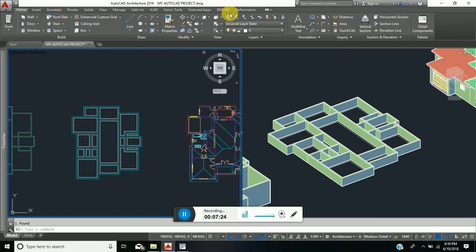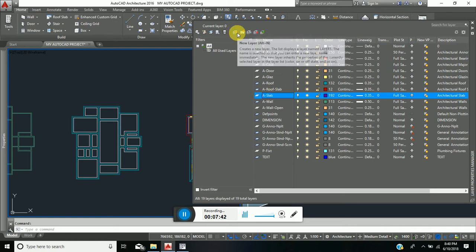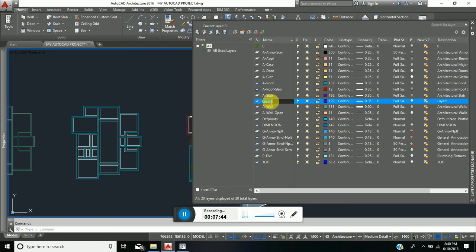And so to do that, I'm going to go over to my layer properties, and let me open my layers manager, and just below slab I'm going to be creating a new one. So let's go for new. Notice I deliberately created it below that because I wanted the same color. The only thing I wanted to change was the line type. Alright, and so I'm going to be calling this layer foundations, in abbreviation FDN.